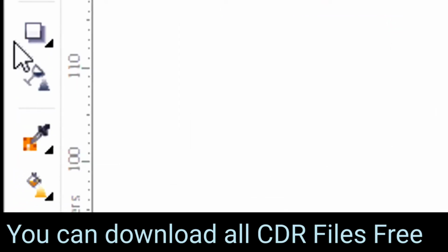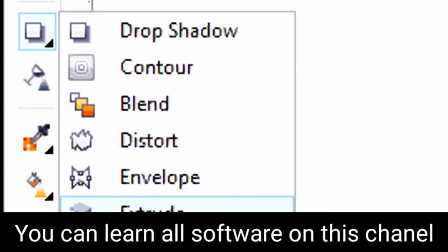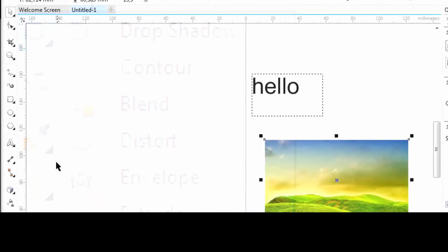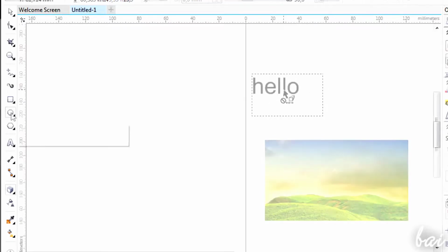All you need to create 3D objects is inside a tool called the Extrude tool. Keep in mind that this tool works on vector curves only. If you try it on paragraphs or bitmap images, nothing will happen. If you want to know how to make 3D text, watch the related video in this guide.